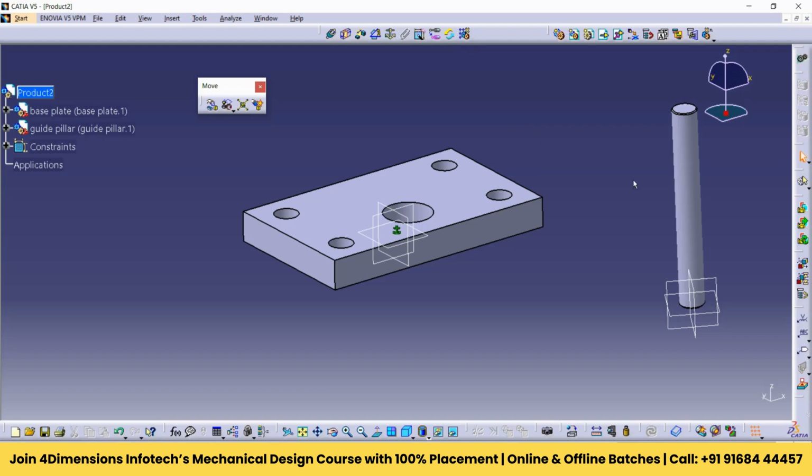So in assembly, whichever part we are going to assemble here by using pattern command, that is reuse pattern, the related feature should also be made by pattern command only in part modeling, and then only we can make them pattern here in assembly.